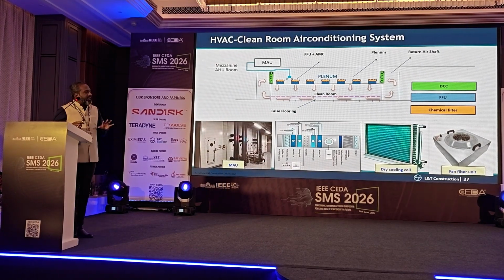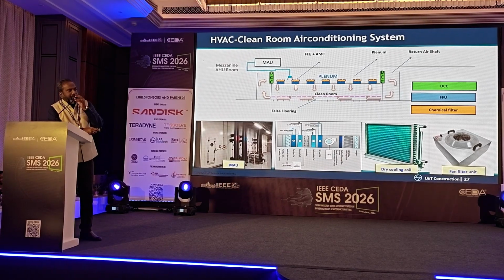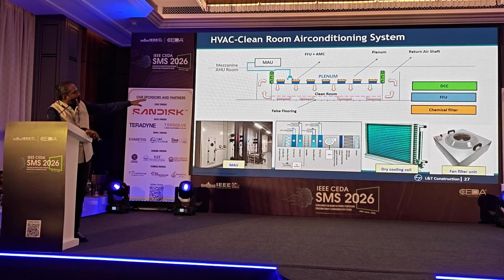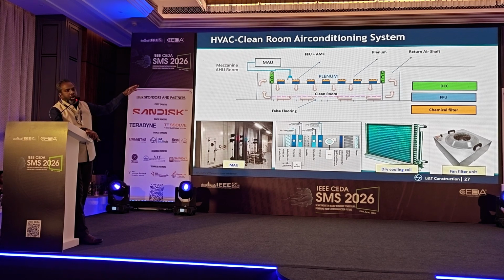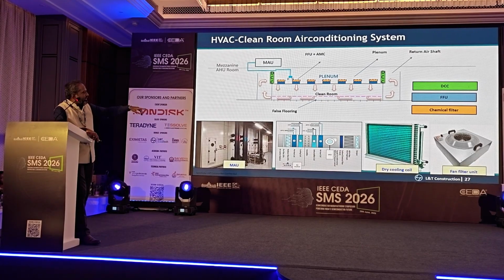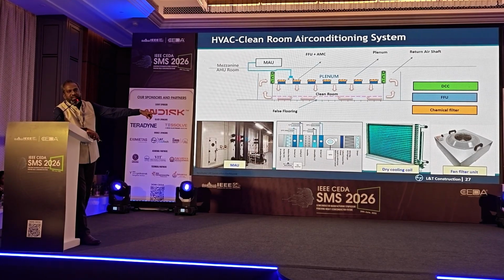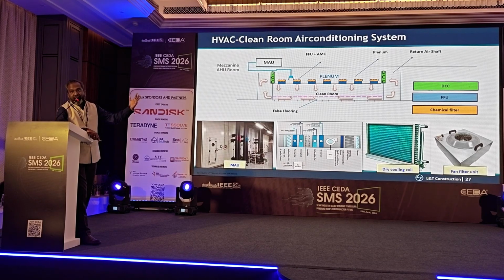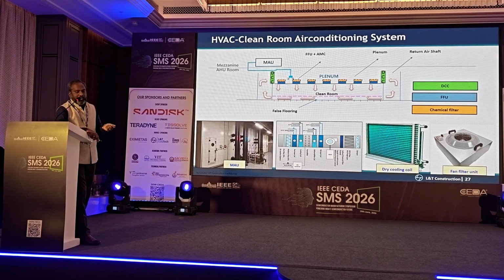That's very typical of HVAC. You see the clean room. From the top, we have the air pushed in through the false ceiling through fan filter units. On the right, what you see is fan filter units. Each would have a HEPA filter or higher, so that all the particles get filtered out.